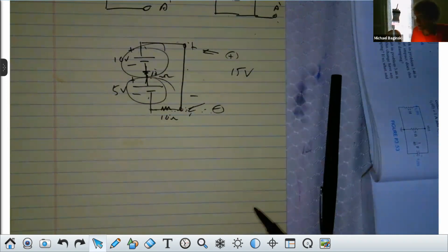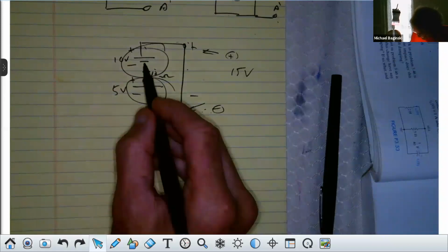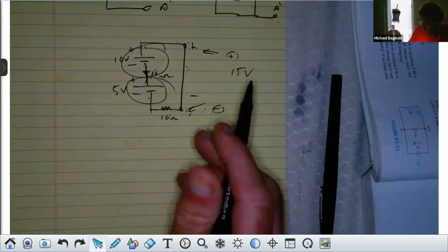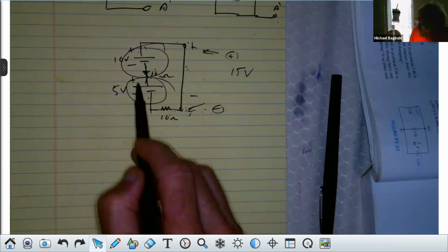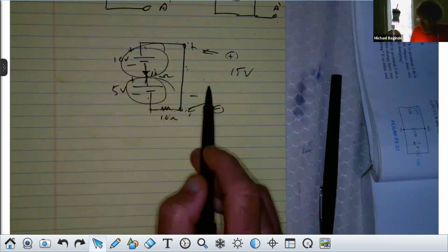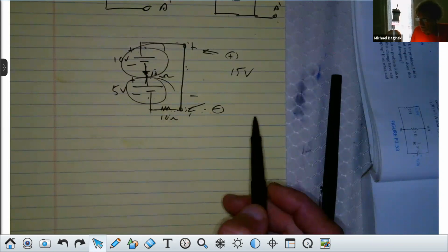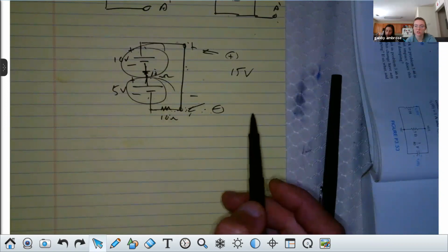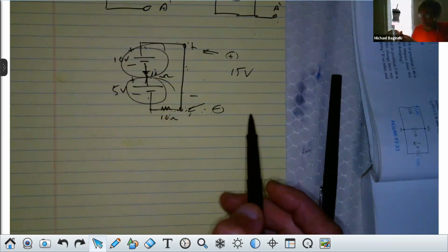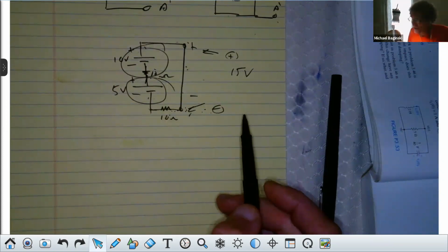Right? That's it. Voltage is like a pressure. It doesn't matter if there's one voltage source here, another here, as long as the amount, when they're added with no current flowing, is 15 volts, the current will be limited by the 15 volts. It would be whatever. So as long as they're in series, you can add them? Yes. Okie dokie. Yes. Thanks.